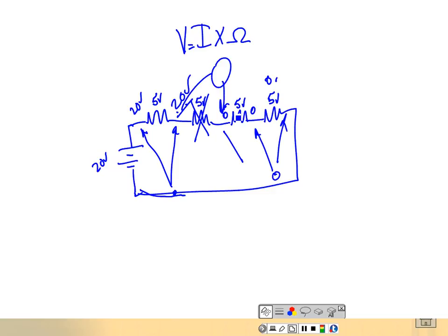So if I measured across these switches right here, I would measure 120 volts. If I measured across these switches right here, I would measure 0 volts, if the switch was good. Now they're going to drop just a tiny bit, but it's not going to be enough to produce any work, because there's no such thing as 0 resistance, right? But it's going to be so close. So if I've got a light switch that's dropping 3 volts, then what do you need to do? First of all, it's going to get hot. What do you need to do? You need to change that sucker out.